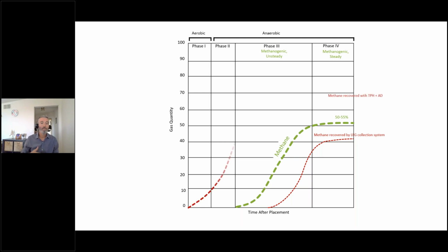Next. If we were to have an organics recycling facility, anaerobic digesters co-located at the landfill, a system composed of a thermal pressure hydrolysis combined with anaerobic digestion, like the one shown before, methane will be captured as soon as waste enters the site, right? Here shown in the upper red line. Why do we have more gas? You might be wondering. Because we are capturing the full methanogenic potential per ton of biodegradable waste. We are bringing 20 years of gas to right now. Next, please.